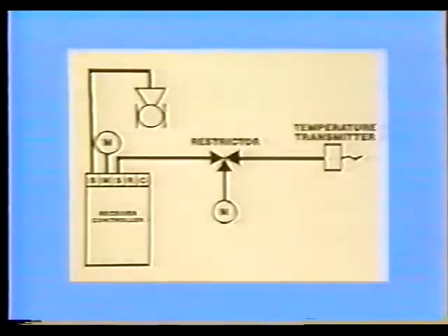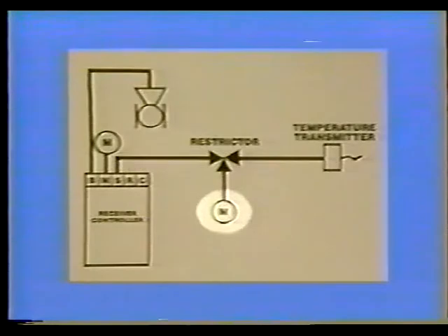Now, let's take a look at how the transmitter operates. These principles are true for all of the transmitters in our product line and most competitive devices available in the HVAC industry. The operation of the transmitter is dependent upon a constant source of main air supply. This source should be maintained at 20 psig.